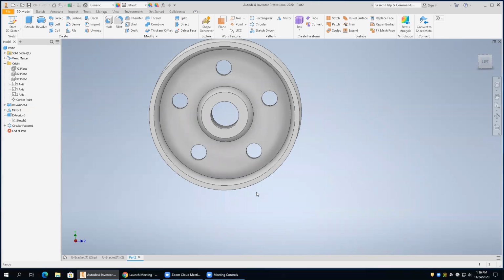You can adjust the one. And because this is the sketch that drives these guys, I could change that sketch up. If I change the diameter, those would all change because it's based on that sketch. So remember, everything's parent-child, parent-child, parent-child, the way it's working.